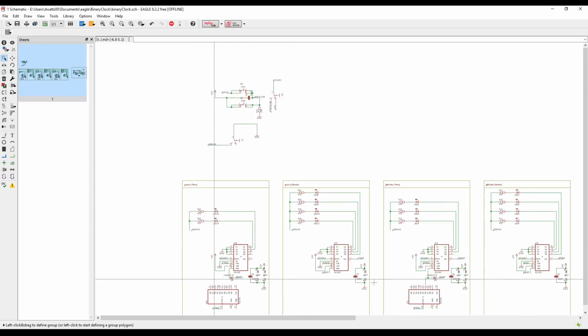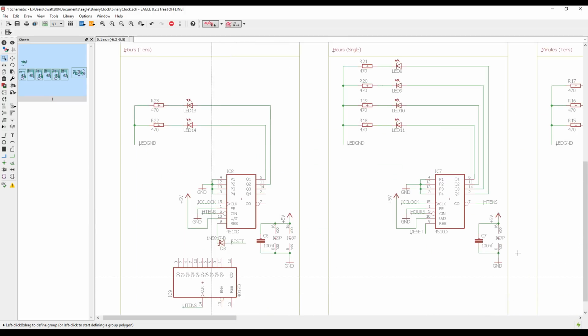Problem is with these ICs, these little CMOS ones, right? If you've put them in a circuit and you've got, you know, the stray voltage. If you run your finger down the pins, you can affect these things. You can trigger the clock. So when you just switch it on, there's so much going on in that circuit that they add sort of random counts on. They've got random things in their sort of memory already. So resetting is essential. So I've got to do that.